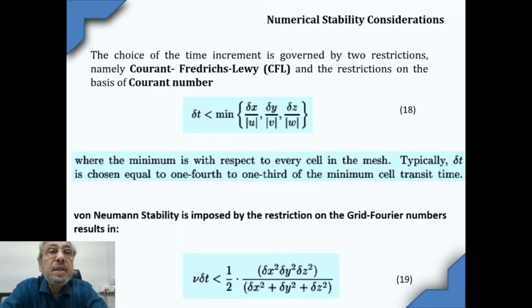Having said this, we have covered basic flow solution strategy, boundary conditions, all related to pressure velocity iteration. Now we can see that since our governing equation is elliptic in space, parabolic in time, we will basically march in time direction.